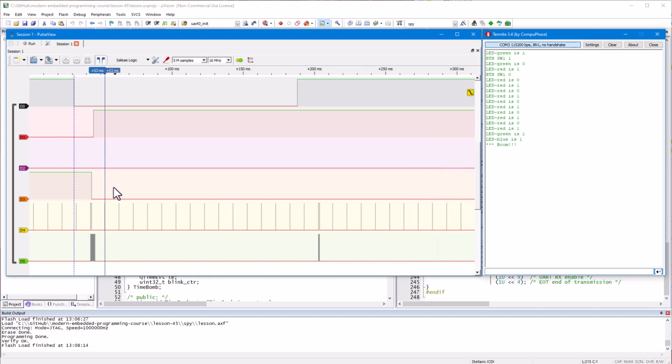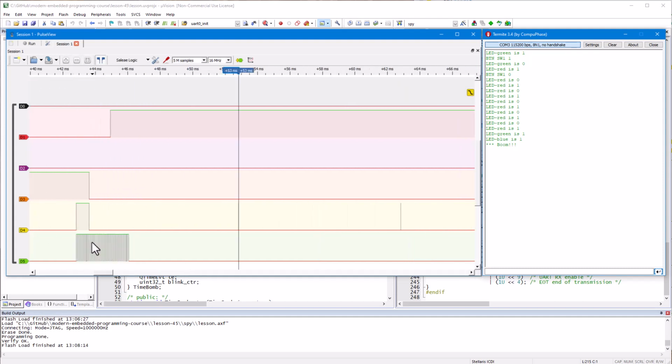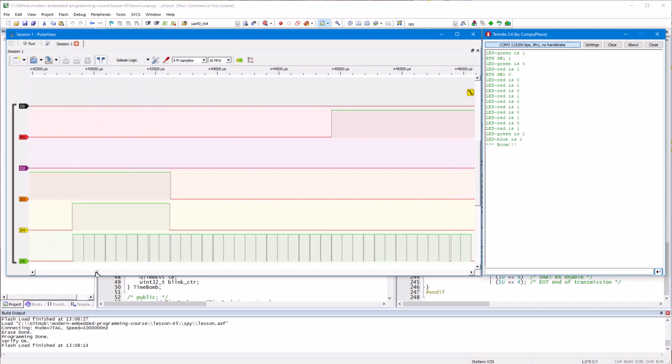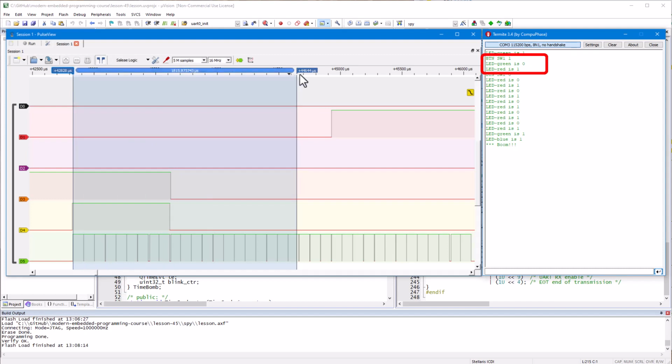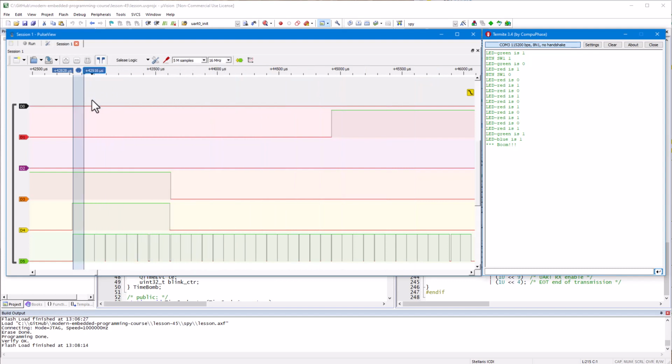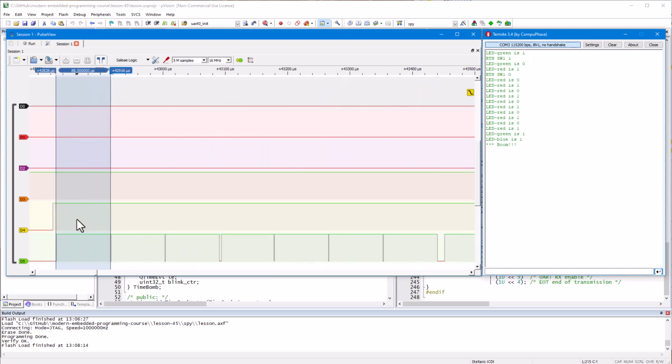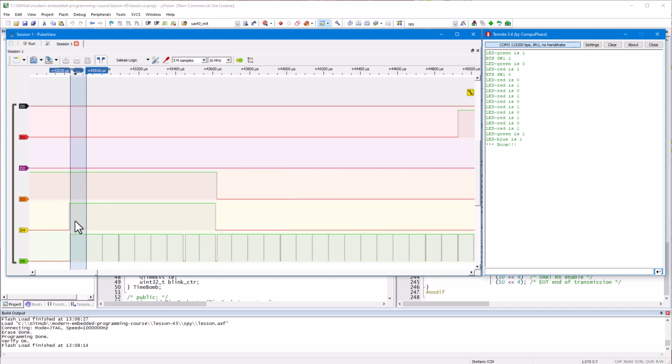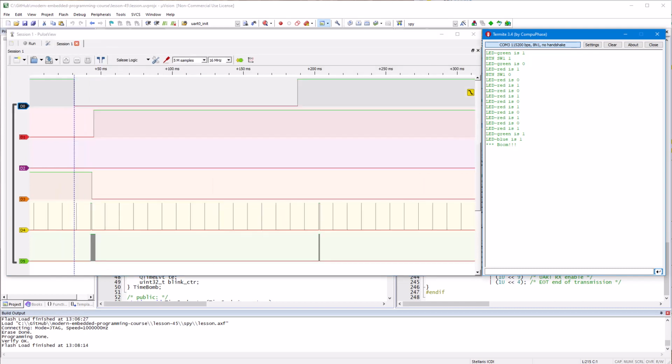Trace D5 shows the activity inside the fputc function, which is even worse. This is because it shows all 3 printf messages produced. All of that takes some 3.2 milliseconds. Actually, here you can count the individual bytes transmitted, whereas each byte takes 87 microseconds to send. Overall, this is pretty bad.